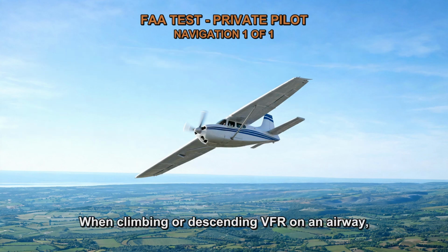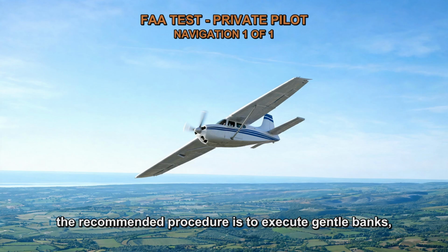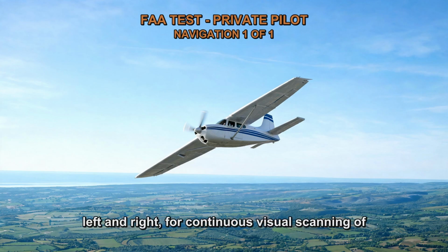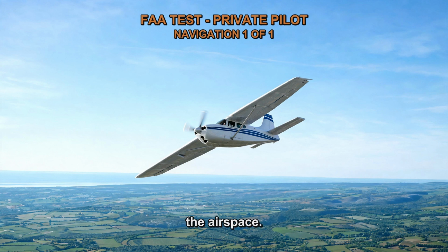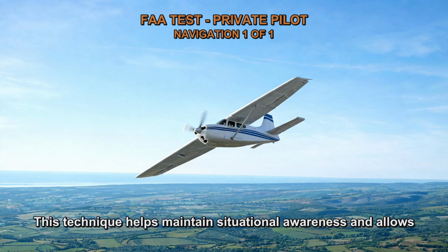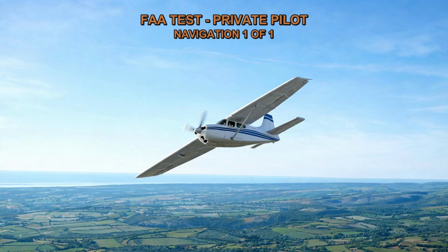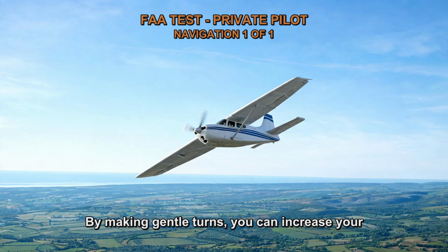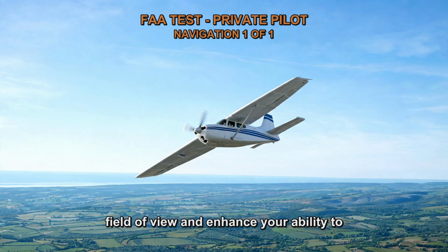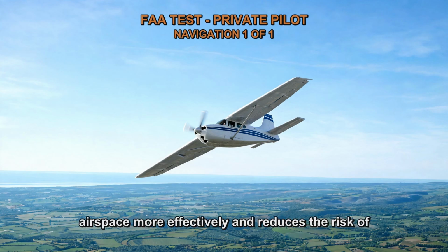When climbing or descending VFR on an airway, the recommended procedure is to execute gentle banks, left and right, for continuous visual scanning of the airspace. This technique helps maintain situational awareness and allows for better visibility of other aircraft and potential obstacles in the vicinity. By making gentle turns, you can increase your field of view and enhance your ability to detect and avoid any conflicting traffic.